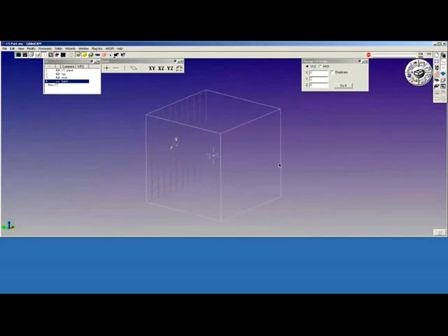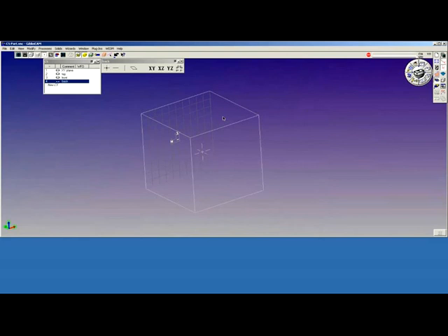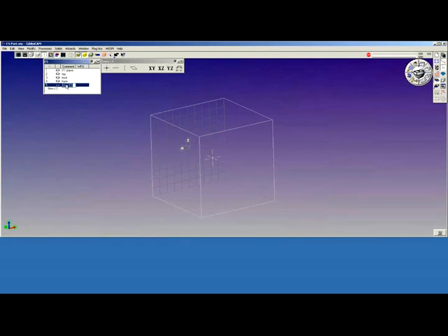So far, we've generated 3 new coordinate systems based on the default. We placed one at the top, one at the front, and one at the back of the cube. I'm going to use a slightly different approach to generate a coordinate system on the right side of this cuboid. Instead of using the change origin tile, I'm going to use the align CS plane. To do so, I build a new CS and I name it right. This is going to be on the right side of my coordinate system.